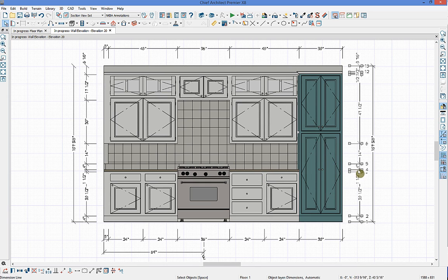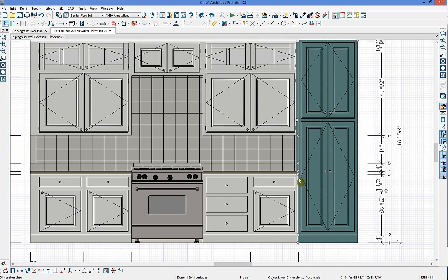So we're just going to click on it twice, and here we can see where all of my points are snapping to. So what I want it to snap to is, I don't actually want to snap to the countertop for right now, and I don't want to snap to the top of the range, so we're just going to pull to remove each of those. And then I don't want to snap to the toe kick at this point either.